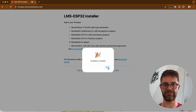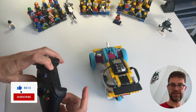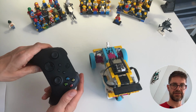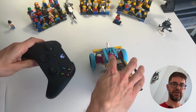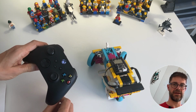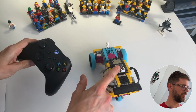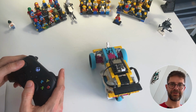Good, installation complete. To pair the gamepad, at least the Xbox 360 gamepad, you press the pairing button here. It starts flashing quickly, and as soon as it detects this board, it will connect, and you can see now there is a solid blink, and now the Xbox gamepad is paired with this chip. It stays paired if you turn the robot on and off, so that's very comfortable.